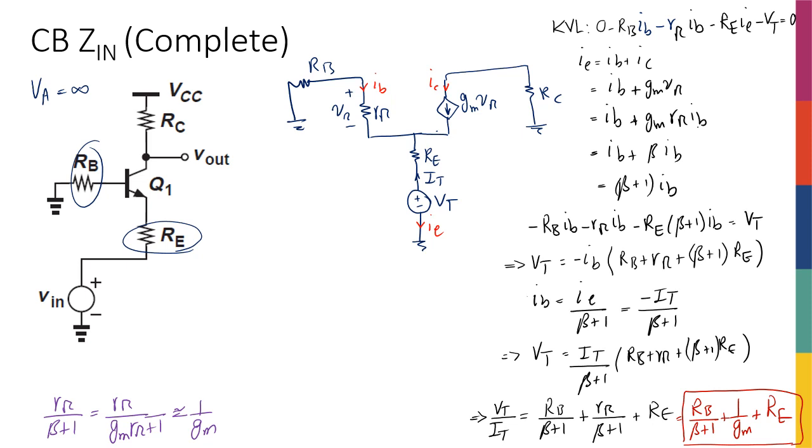And then you might actually make some changes in the circuit, and then I have to remember a new expression. If you think about it, there's some sort of logic in it, and if you remember the logic, then there's no need for you to remember any expression. So if you look at the expression, what it tells you is that the input impedance is the impedance seen by the input source. So the impedance that you see is RE, the resistance that you see in the emitter, okay?